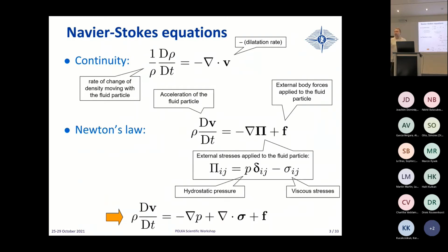And then what we are going to do is to simplify those equations, because solving those equations would effectively give you the acoustic field, but it's a very complicated way to solve for it. There are smarter things to do, and Sophie, in her course, will elaborate on why the acoustic quantities are typically small quantities, the density perturbation, the pressure perturbation, the velocity perturbation, compared to those that characterize the flow or the atmospheric pressure, for example. This will allow us to linearize the equations, and it will considerably facilitate our task to obtain the acoustic field if we proceed through a priori linearization.